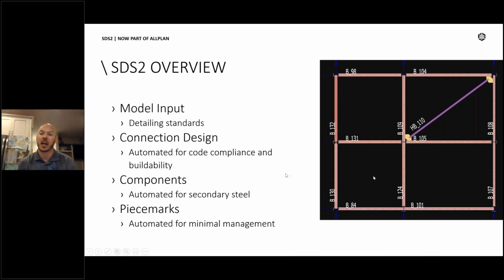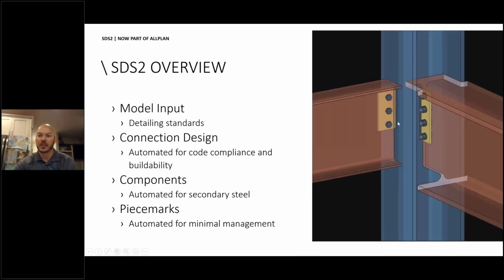Then connection design. As you input the model, there's intelligence to recognize how the members are framing together, and then the connections are designed for code compliance, whether that be the North American code, AISC, the Canadian code, and a few others as well. So buildability, we'll talk about buildability a little bit as we design these connections.